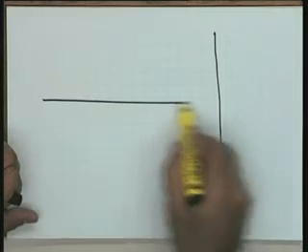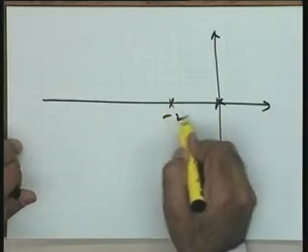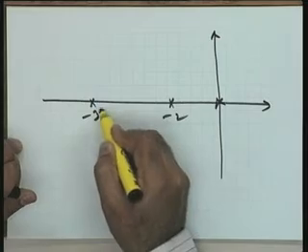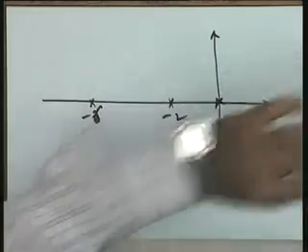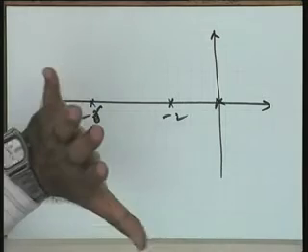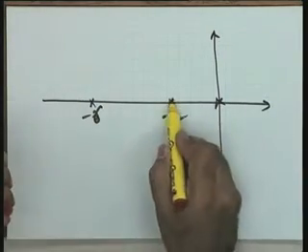Right then, let me quickly go to the other aspect also, so that next time I have the design examples only. And the other aspect I take is the phase lag design or the integral control. You recall this diagram, with poles at -2 and -6. And tell me, if I place a pole at the origin, what will happen to both transient and steady state accuracy? I am drawing my sketch over here.